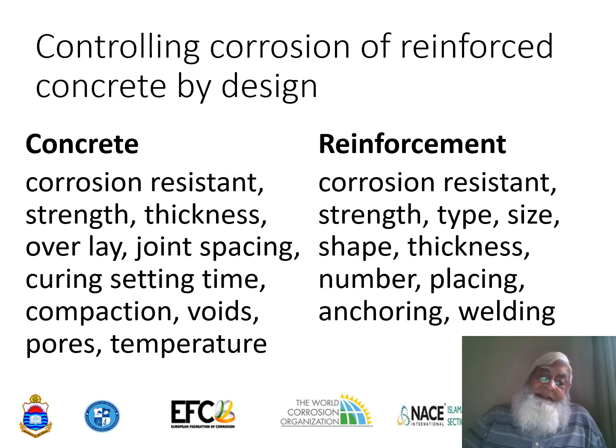And welding of the reinforcements is very important, because if the welding is not done properly, it can develop its own problems and cause cracking of the steel at the weld point, and this tall building can become weak.